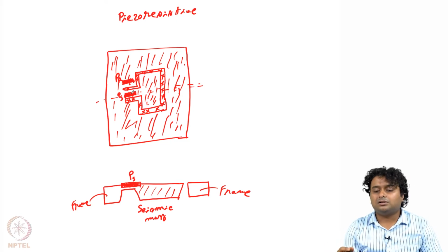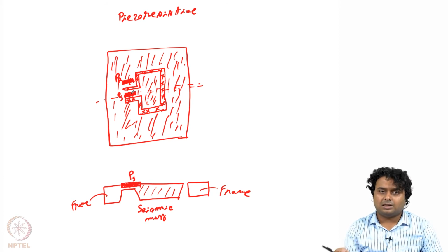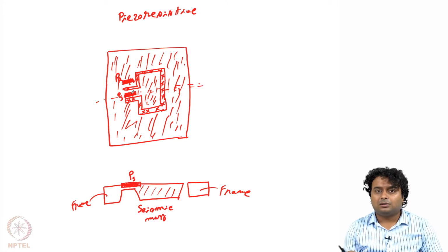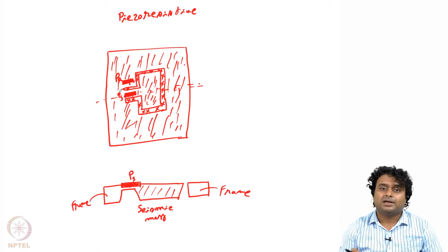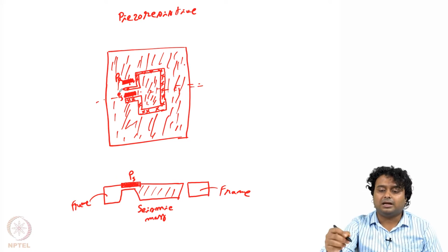The advantage of having this kind of reference resistor is, let us say there is some change because of the temperature or applied voltage or any other parameter which is common to both, the reference resistor as well as the sensing resistor. Those effects will get cancelled out, because if the resistance changes because of temperature, it will change similarly for both of them.